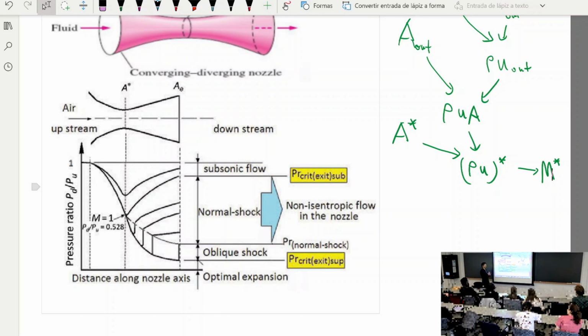Okay? And one way you can think about this is because there is going to be a supersonic region sitting somewhere over here. The flow becomes Mach 1 and now it's supersonic, right? In a supersonic flow, information only propagates downstream. Information cannot propagate upstream. So no matter how you change the condition downstream over here, it cannot go through this supersonic region.